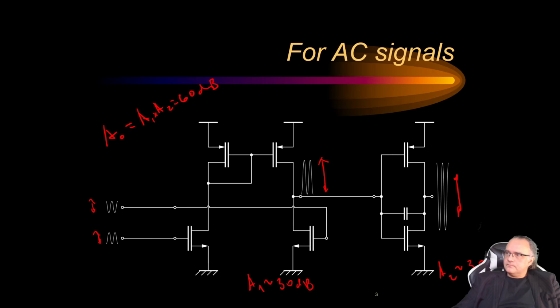Now what is this gain about? So the first stage is a common source amplifier, and the second is a common source amplifier. For a common source amplifier, the gain in the most generic case is the equivalent GM of the stage times the equivalent resistance of the stage, and A2 is respectively GM2 R equivalent 2, so this is R equivalent 1.